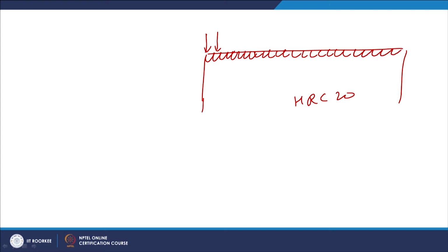And if the steel which had a hardness of HRC 20 is subjected to the remelting at the surface layers followed by the martensitic transformation during the solidification and during the cooling to room temperature, then this kind of fine grain structure plus the presence of pearlite and martensitic mixture at the surface due to the remelting will lead to a significant increase in hardness from 20 HRC to maybe say 40 to 50 HRC.